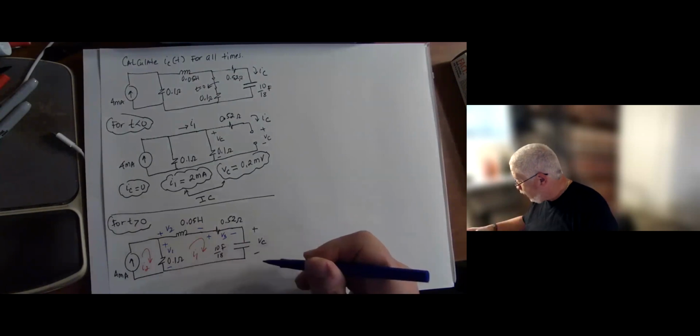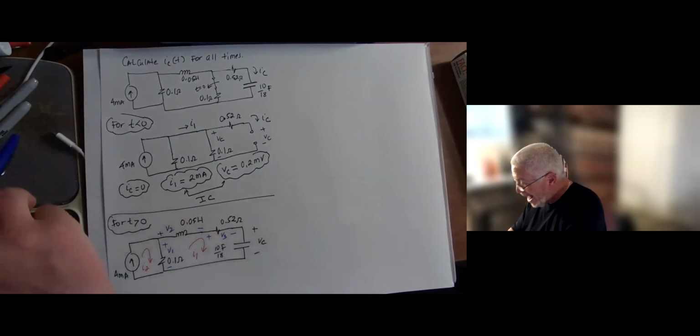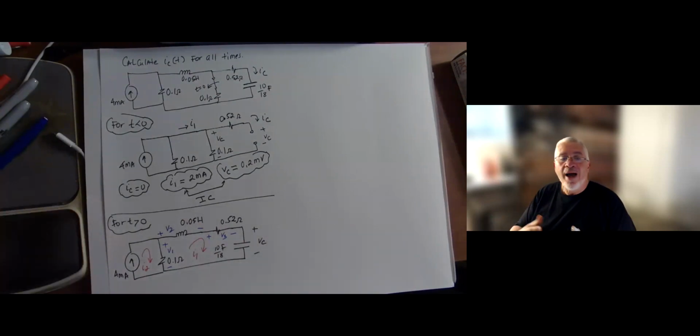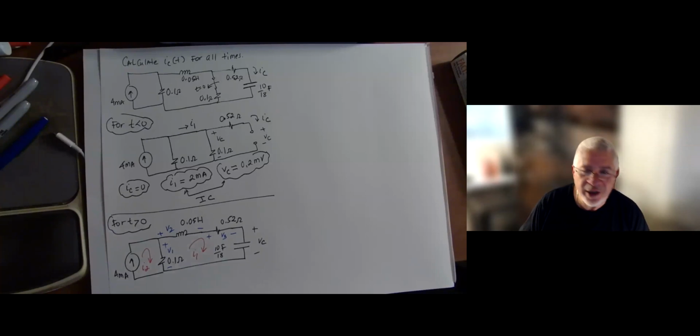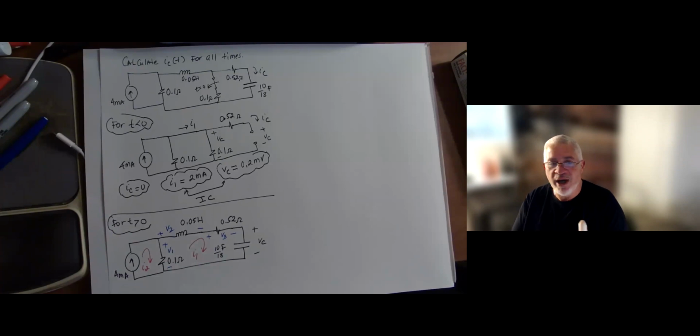Of course, the capacitor already has a voltage, so I don't add another voltage to it here. So I'll prepare the circuit for a mesh solution. Whenever we talk about mesh, I want to take a few minutes to talk about how we do mesh for circuits here. Anytime we do mesh, we need to pay attention to current sources.